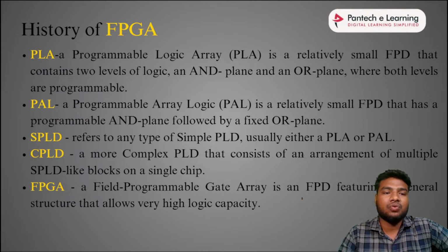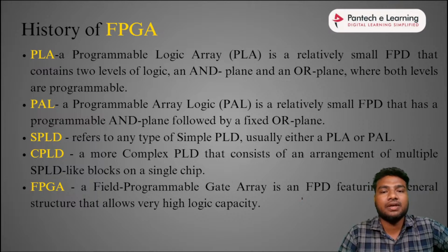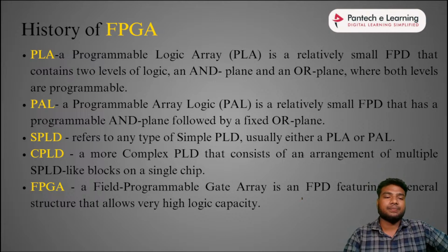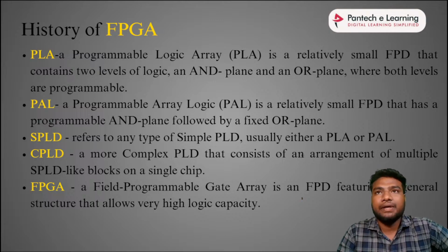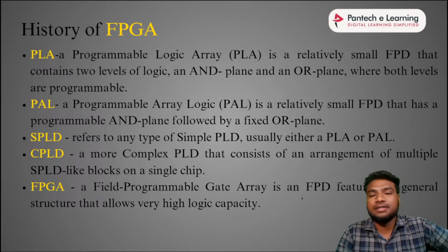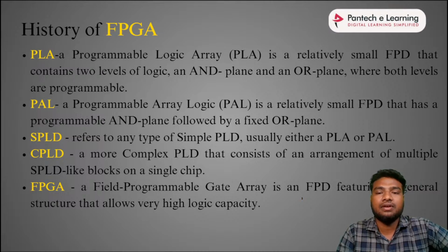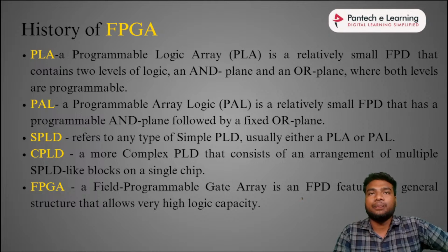Then we move to programmable array logic, PAL. It is also the same. It has an AND plane and an OR plane, but here the AND plane is followed by the OR plane. Firstly it has the AND plane and then the OR plane. This is the difference from the PLA. Then SPLD, a simple PLD. PLD stands for programmable logic device. We can program the device, and it can consist of either PLA or PAL. Either of those methods is contained in a simple PLD, SPLD.